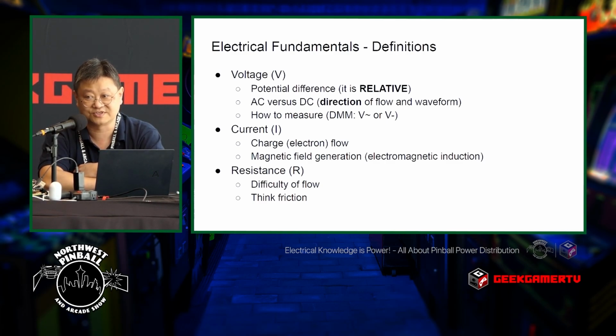And this is the importance of ground. It's always the black lead, typically. It's the black lead on your DMM. And people think, oh, ground is always 0. Well, ground is usually 0. It's not always 0. Again, it depends what floor you come into the building as to where your 0 point is.